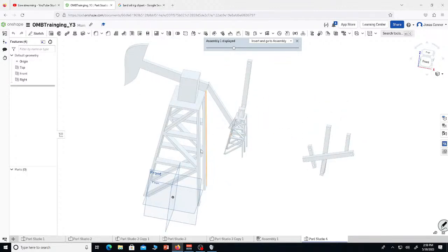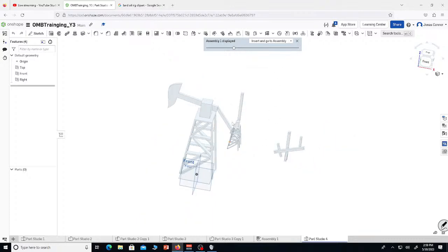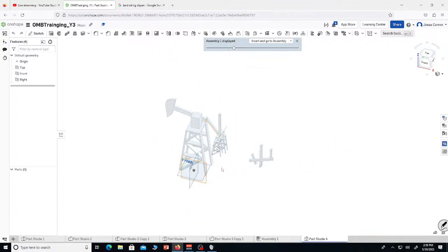And where this is really useful is I can just have the robot and then create a part studio around the robot. So if I need to update a part, it'll let me essentially create a part studio on top of the robot, which is really nice. And I can just butcher it however I need to make it work properly. It's very useful. Probably one of the best tools you can have for refining specific part designs.